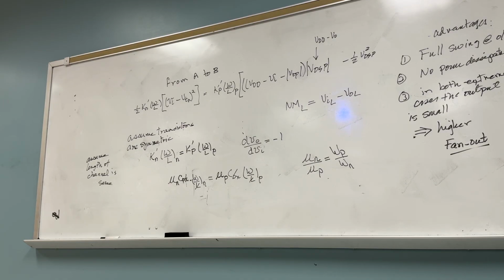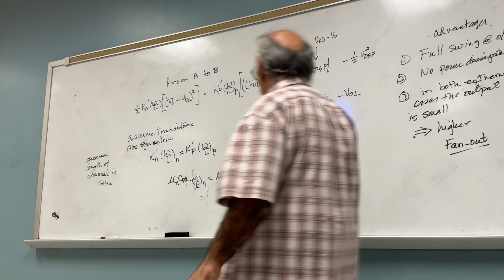Symmetric. Clear? Now, shortly, again next week, I will show you that the transistors being symmetric might not be the best solution. Because remember, as you increase W, the width of the channel, you are going to use more space. Did you get it or not? And the capacitance also will change. Clear? But we'll talk about that shortly. Let's not worry about that.